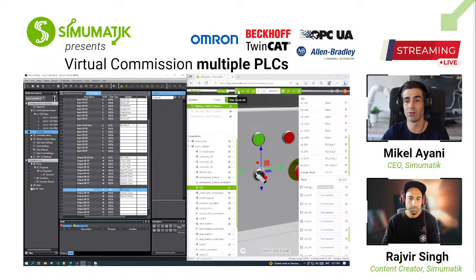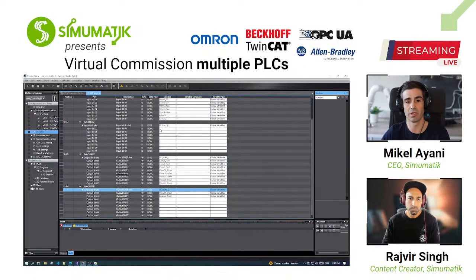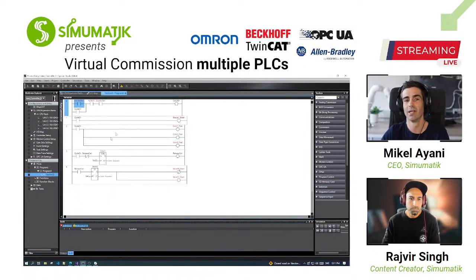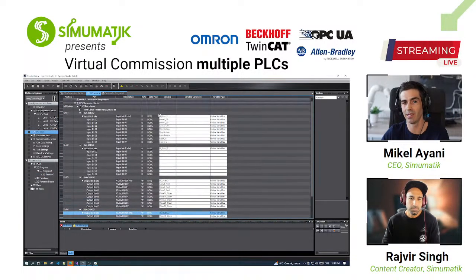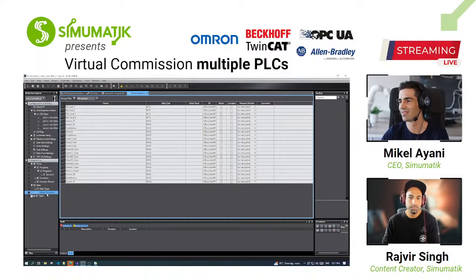The good thing is that once you do this, you can go to your program and make use of those variables you used in the mapping in the code. Why? Because automatically, once you map an input bit or the entire card, all those become global variables. And the amazing thing with the integration is that Simumatik can reach all these global variables, so seamlessly it will be writing in these two bytes, reading these two bytes, and the rest will just be mapped accordingly.